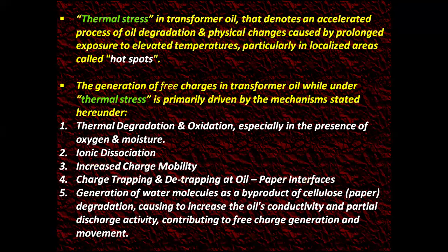The generation of free charges in transformer oil under thermal stress is primarily driven by the mechanisms stated hereunder. Number one, thermal degradation and oxidation, especially in the presence of oxygen and moisture.